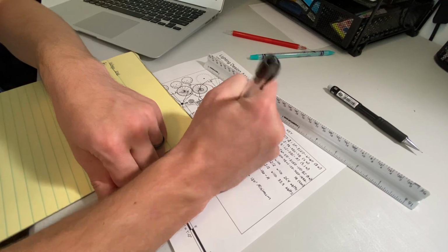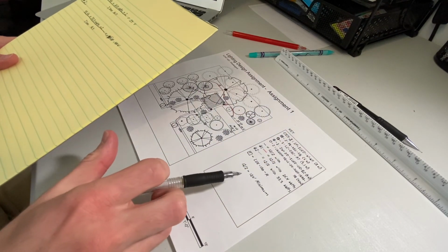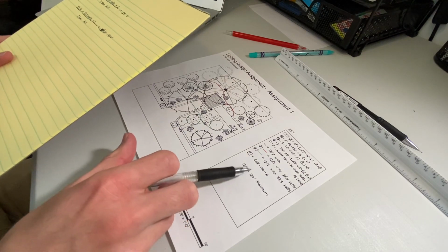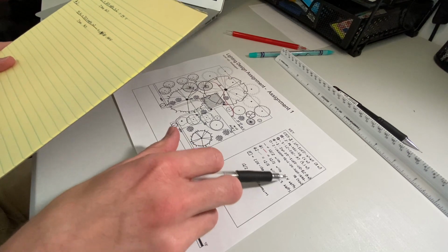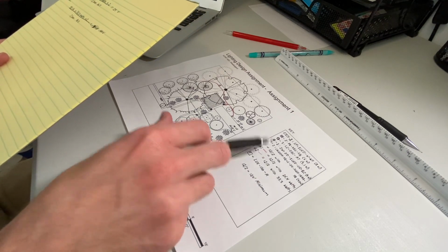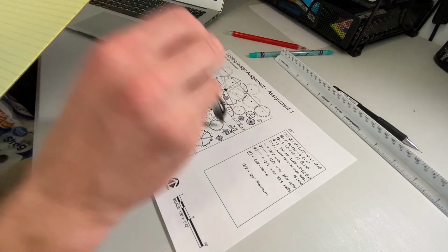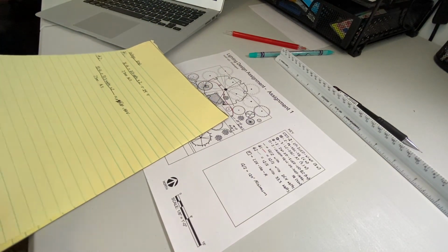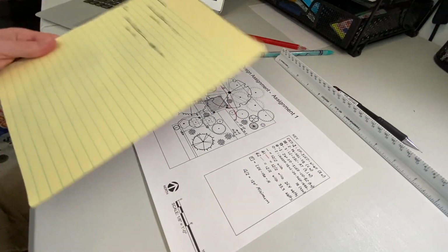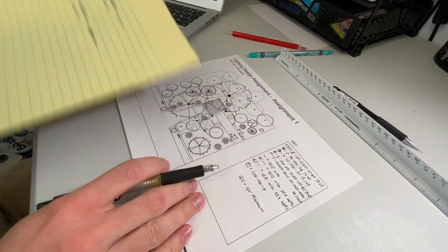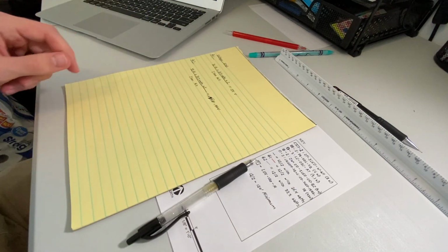And then at the end of this, you would write the voltage drop so that they know. That's everything. You have the length of needed wire, you have all the products listed with its watts, you have the wattage per line, you have the wire that you're using, and you should be set. You did the voltage drop, and we have here the calculations, and this is how you do a simple lighting design for a landscape. So thanks for watching.